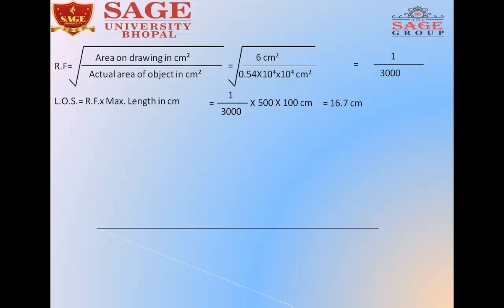So you will take 5 divisions. Now you will divide this line into 5 equal divisions, and you will mark 0, 100, 200, 300, 400 to the right, because we leave the first portion as 0 to the left. In this portion we read the subunit of the main unit.